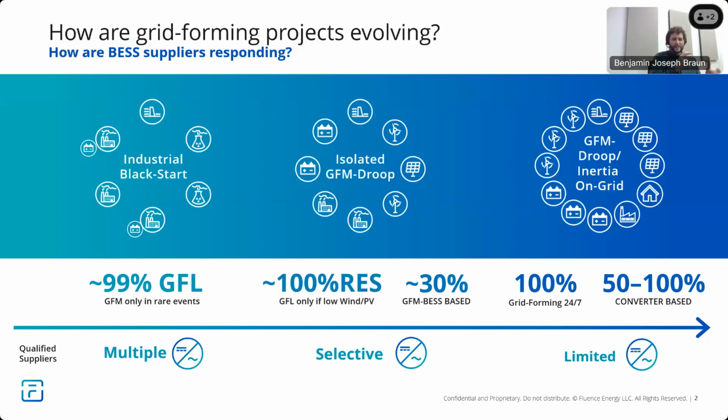And then we started to see that not all of our converter suppliers have the grid forming capabilities that we need for such applications. And as time has progressed and as more and more renewables have come on the grid, we start to see that even in mainland or continental or large scale bulk power systems, the amount of renewable, non-synchronous penetration is so high that even these systems are now in need of something to support either the voltage and/or the frequency or both.